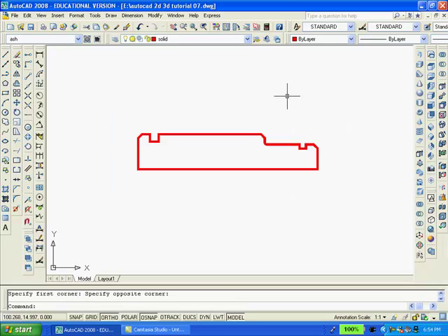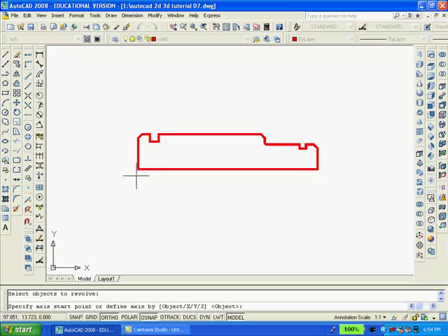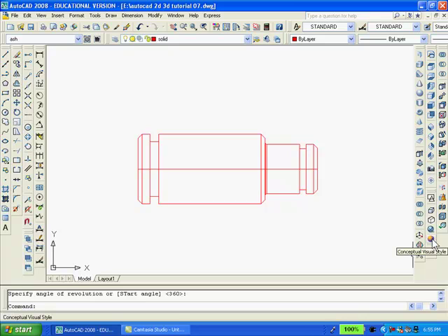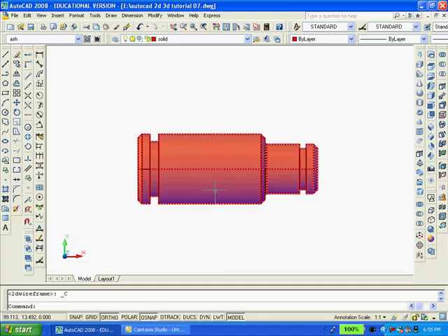And now, because I have a continuous polyline, I'll be able to revolve this object. Typed REV, select the object, select one endpoint and move it to the other endpoint, enter. The object is revolved. Also, this would be a good time to thaw the dimension layer and also to add a little color using the conceptual visual style, and then zoom to see the whole drawing.